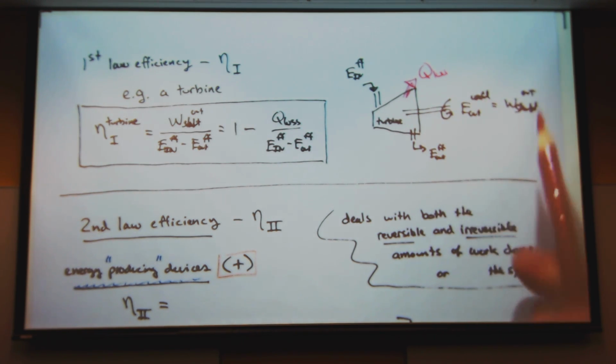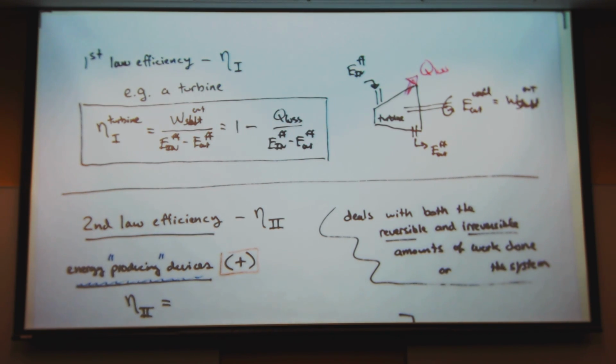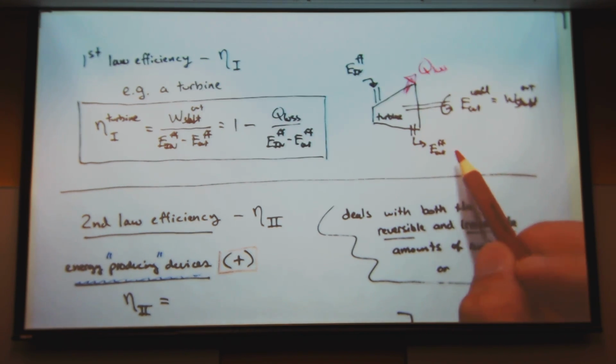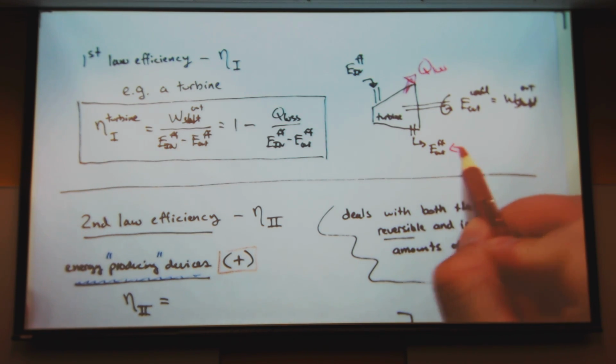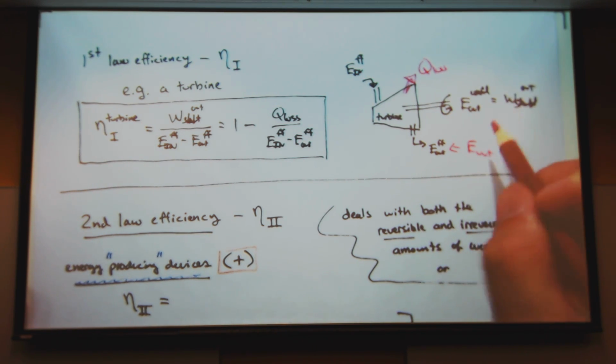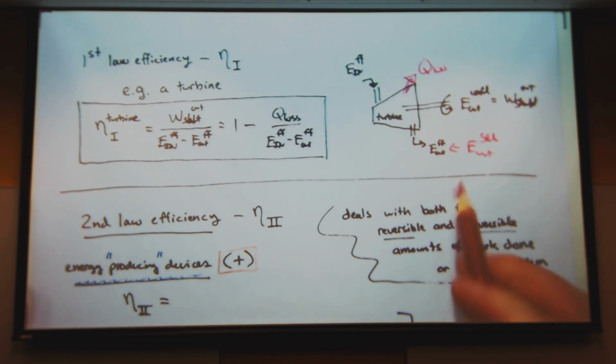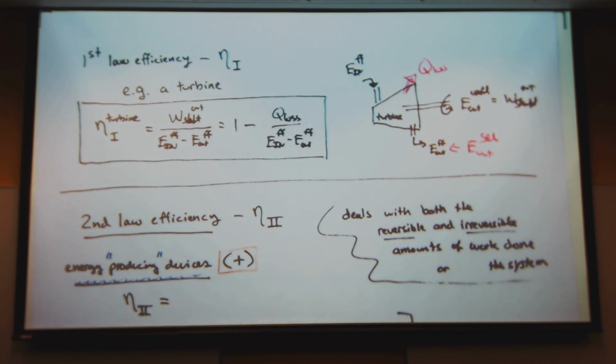You don't output fluid at 0 Kelvin, zero velocity. You don't output a fluid that's static and is at absolute 0 temperature. So there's always going to be some internal energy and kinetic energy associated with that fluid out. So you never really converted it all. Now this stuff is still useful. So this is my energy out and then still usable, right? I could still do something with it.